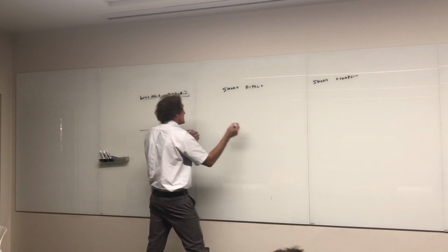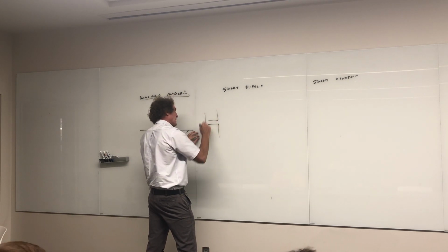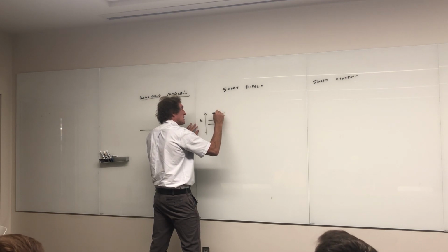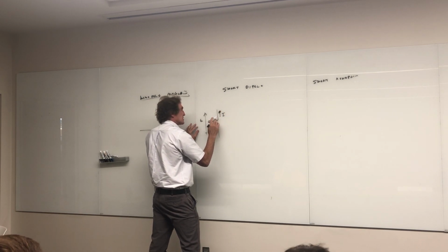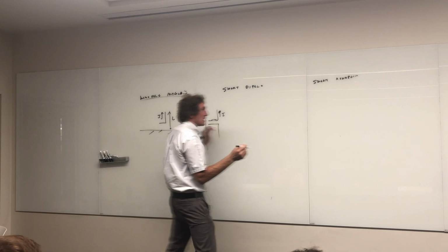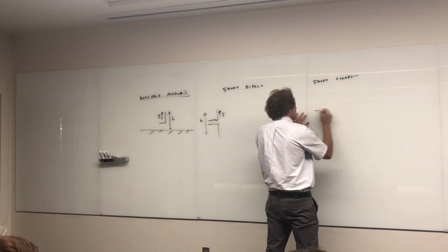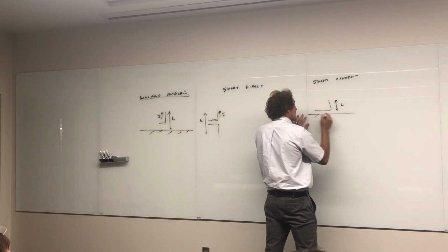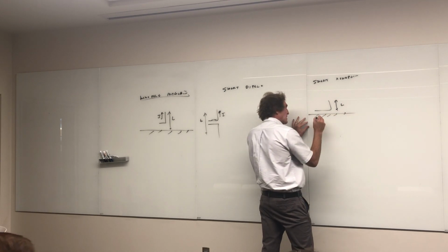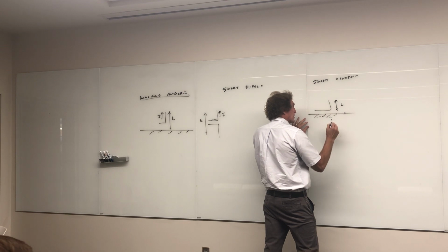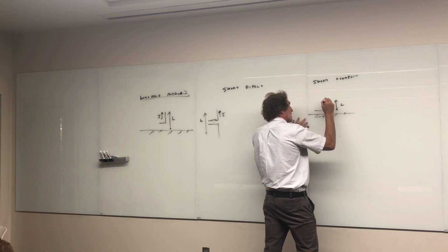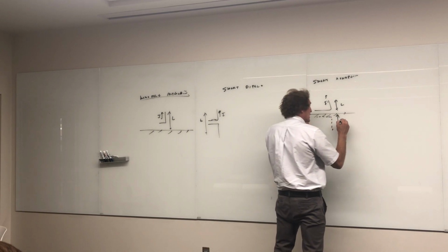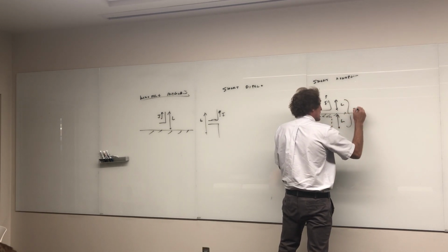The dipole has a length L and an assumed current I. This would be the current right here, as it's coming in. For the monopole, it just has a length L. It's over this ground, but there's an image current right here. This has a current I as well, going up. And the total effective length here would be 2L.